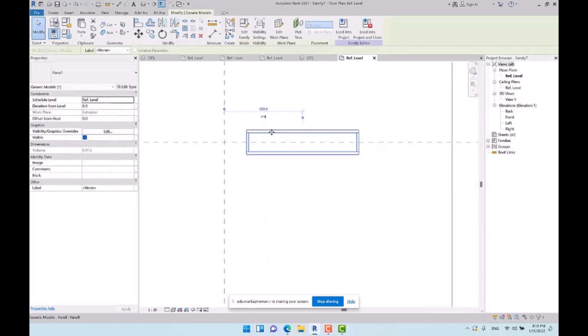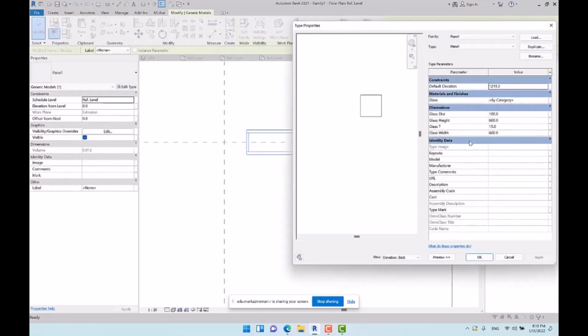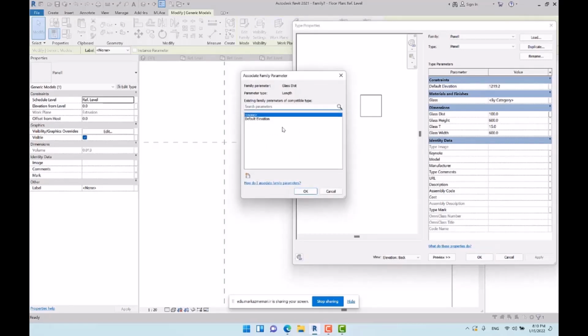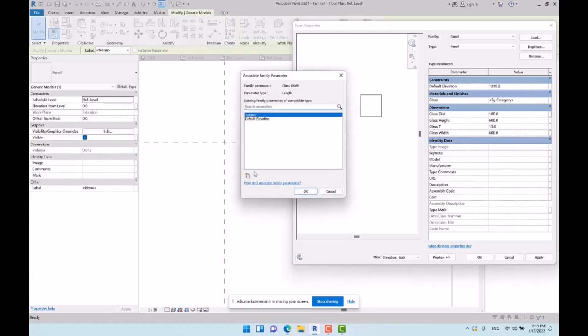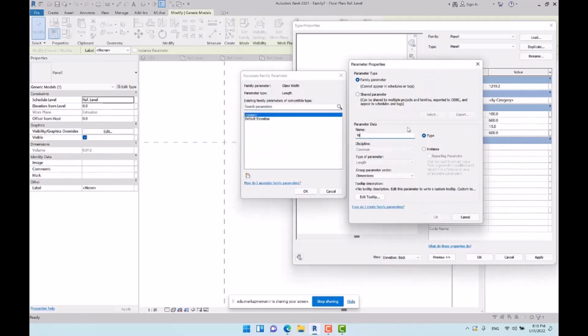Very well. But we should associate all of these 4 parameters at this template file, since then we're gonna load it into our project and the parameters should be associated. We should create 4 parameters again for each of them, but to just save my time, I create one for width and height.